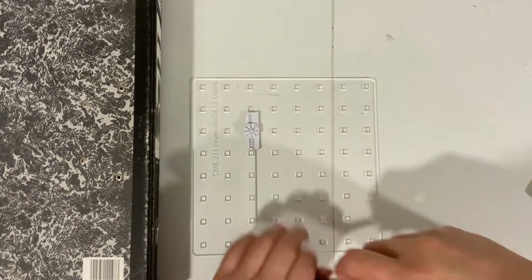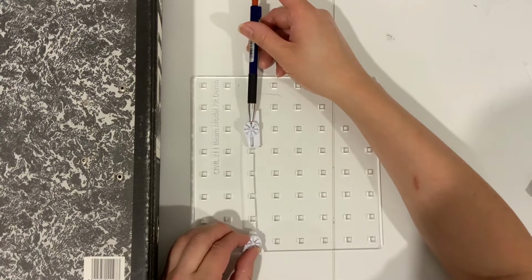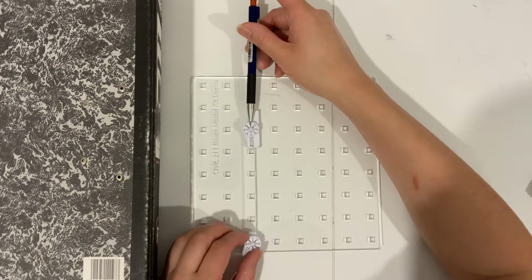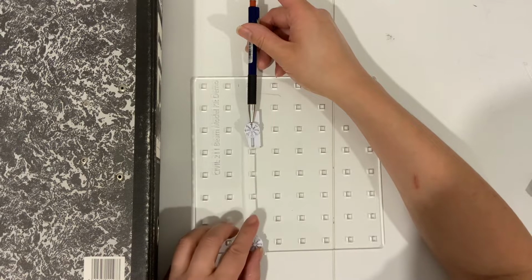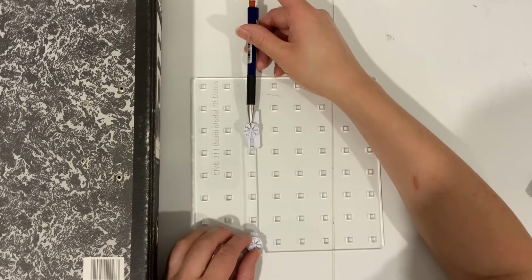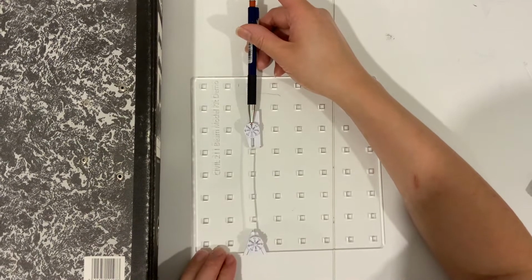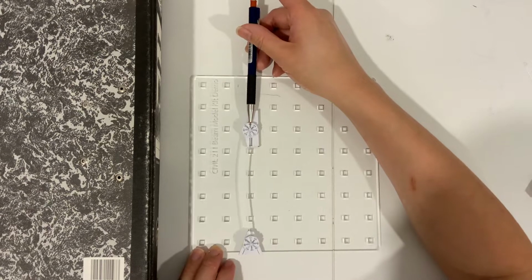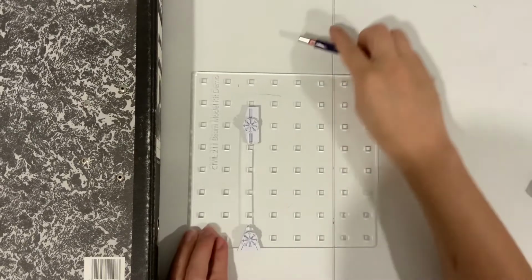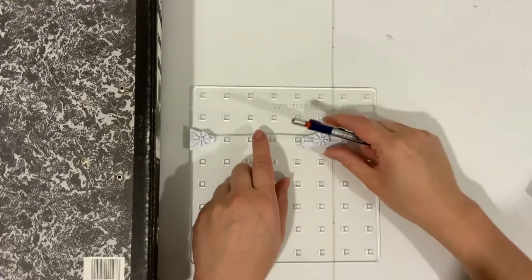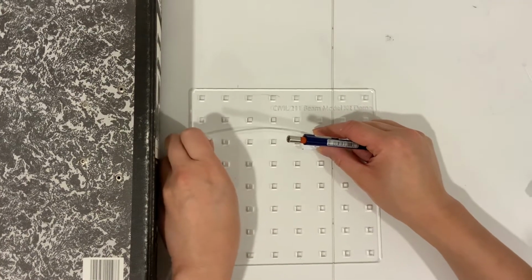So buckling is not the same as bending, and we'll just have a look at some of the subtleties of the equations later on. But what I would be trying to show is that a column will not be able to take more than the buckling load. So I'm not able to compress this without it buckling. So suddenly you see it buckling like that. So I'm not able to put a force on without it suddenly shooting out sideways. Now with bending, if I stuck a load down there, it will go in that direction, and if I stuck the opposite load, it will go in that direction up there.